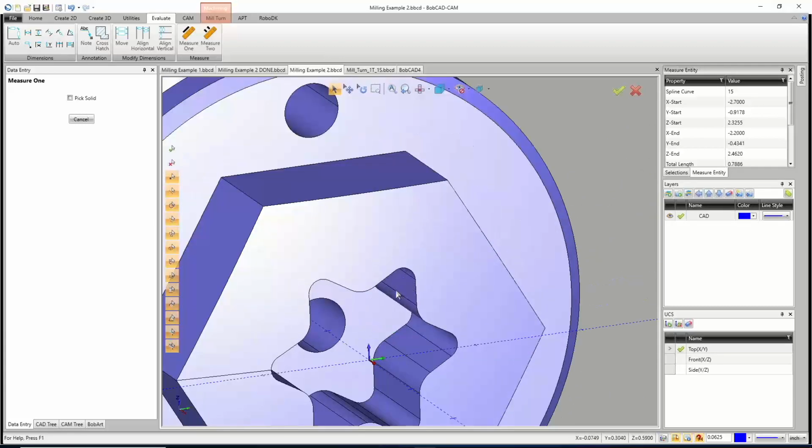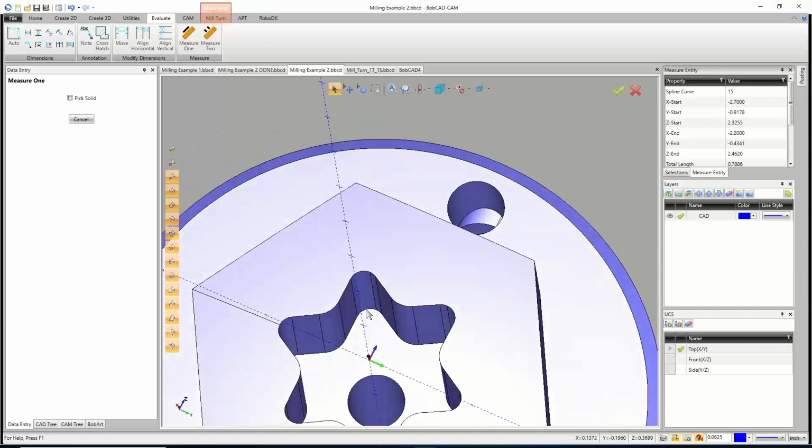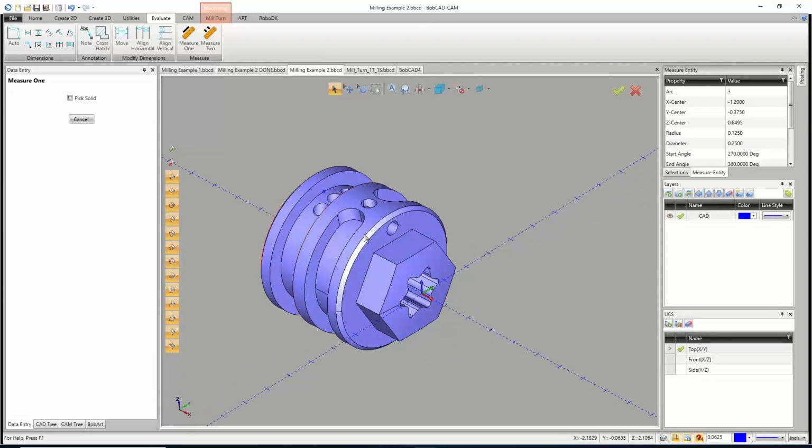These ones right on the front face here, we could take a measurement of that arc on the inside and find out what radius can fit in there. So again, read it as an arc, and it looks like if we use a 1/4 inch tool, we should be fine. So we use a 1/4 inch tool, that'll do the inside. It'll do this outside area as well. We need to set up some cross drills, and again, we'll use just a 1/4 inch or 3/8. We'll figure it out when we do it.